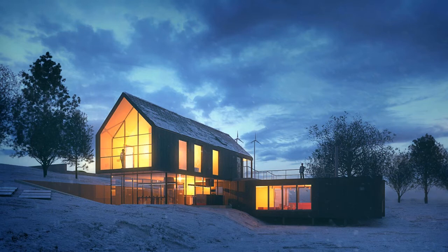You can do similar things with raindrops, with puddles on the ground, again using advanced material techniques inside of the VRMat Editor. If you've got a visualization specialist, they may use V-Ray for 3ds Max. They can create V-Ray VRMats inside of 3ds Max that you can actually use as override materials inside of V-Ray for Revit.